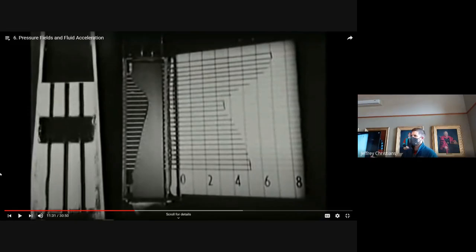And so he said we come in with some pressure, some amount of total energy, pressure and velocity. We get pinched down at this throat, and we have to exchange pressure for velocity. Pressure goes down, velocity goes up.